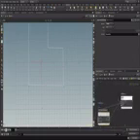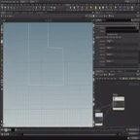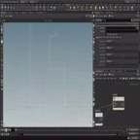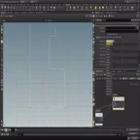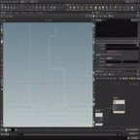In this result, we're going to wire it in, and then I want our input 1 to be the second input. And we're going to have one output, and that is an array of integer numbers, because we're going to get the prim points of this primitive. So we're going to set it to integer array, and then we're going to type in $prim points.